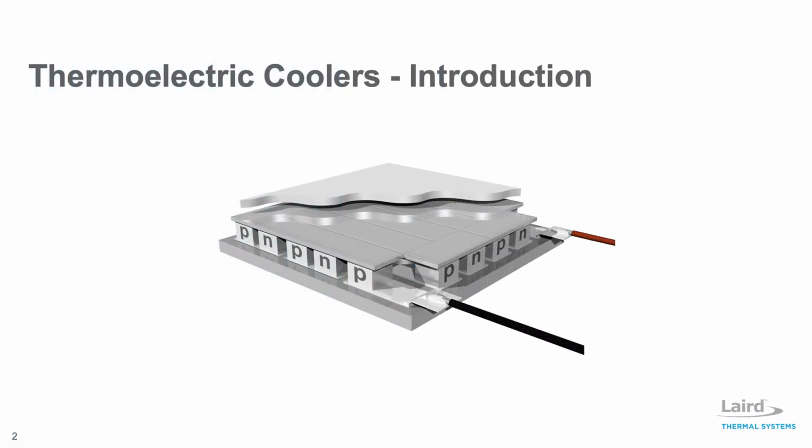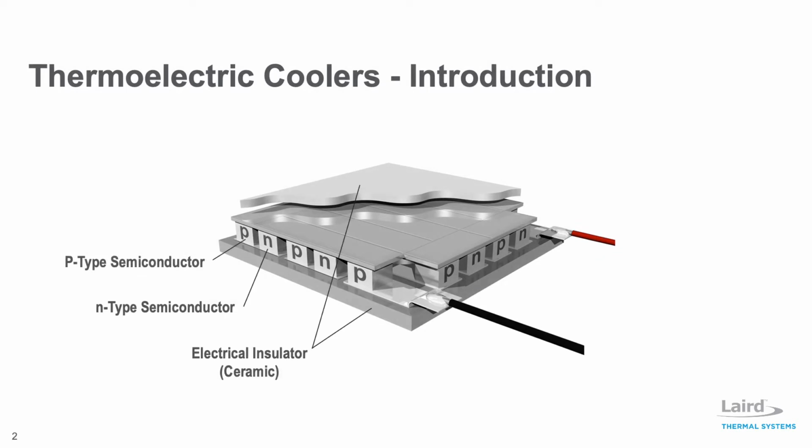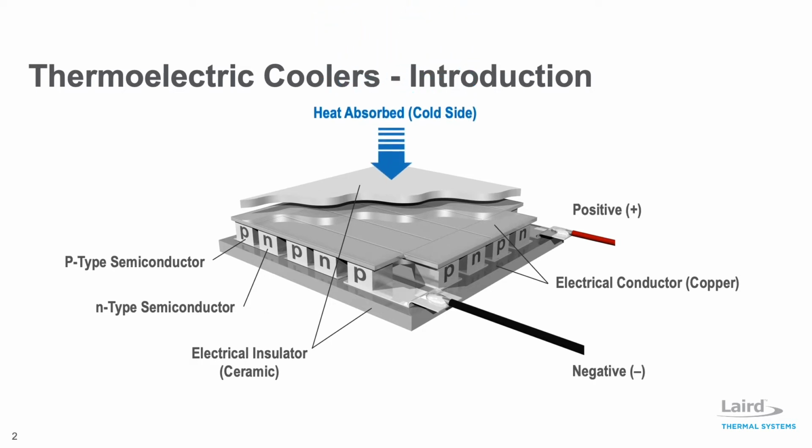A thermoelectric cooler is a small device that creates a temperature differential across the module when DC power is applied. This phenomenon is known as the Peltier effect. A thermoelectric cooler is composed of two ceramic substrates and thermally insulating N and P-type semiconductor elements. Bismuth telluride is preferred as the semiconductor material because it offers very good temperature differential properties in a room temperature environment. Thermoelectric coolers are primarily used in cooling applications below ambient.